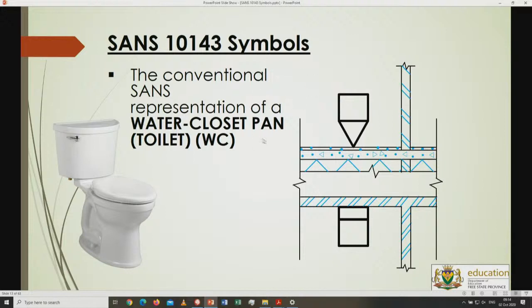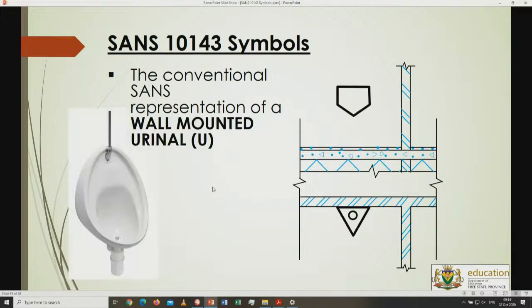Now, if the examiner is asking you to draw the front and the top view, remember, first angle orthographic projection means that the front view will be on the top, and if you look through your drawing, through your XY downwards, this will be the top view. So you can't swap these two drawings around if the examiner is asking you to draw the symbol freehand and then put them next to each other, or put them one above the other instead of like it is over here, front view and top view onto each other. All right, so that is very important, the placement of those ones as well. All right, so for all symbols.